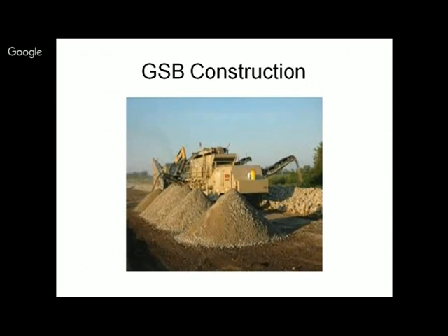The second is you need to check the grading, and you need to select the grading. There are 6 gradings, 3 close graded and 3 coarse graded depending on the sieve size requirement. Any material first should meet the grading and then you should check the CBR value,